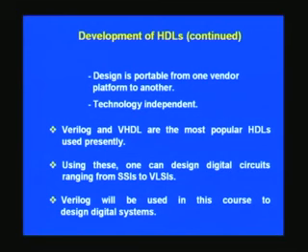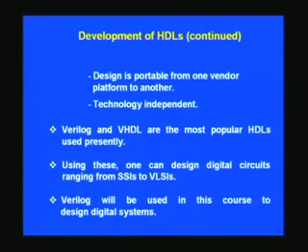And it is needless to emphasize that Verilog HDL can be used in circuit design ranging from SSIs to VLSIs. So you may regard up to 500 transistors to be falling in the SSI category, and beyond that and below 5000 for MSIs, and beyond 5000 up to 50,000 these are LSIs, and beyond that they are termed as VLSIs. There are a number of transistors I am speaking of. We will be using Verilog in this course for digital VLSI system design.